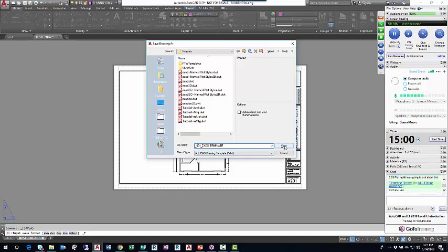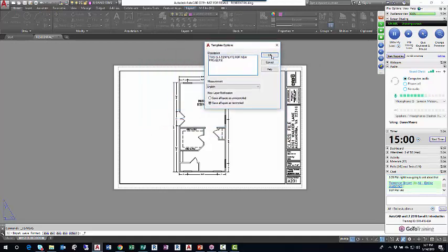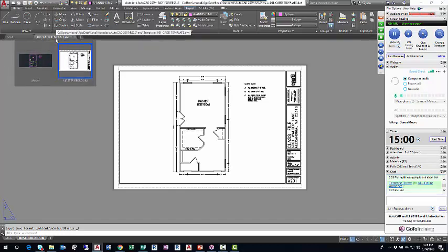I'll go ahead and click save, and then it opens up this dialog, do you want to describe this template? I was like, I don't really need to, but I'll say this is a template for new projects. The description is never for you and I. It's if we share this drawing with somebody else, the description is for them. And once I complete filling out that template options dialog box, I'm no longer in my project drawing. I'm now in the template file.